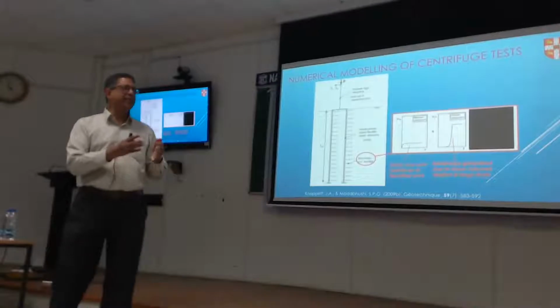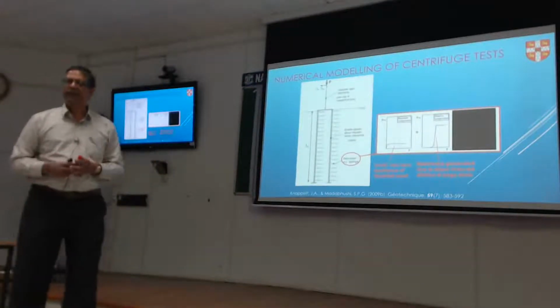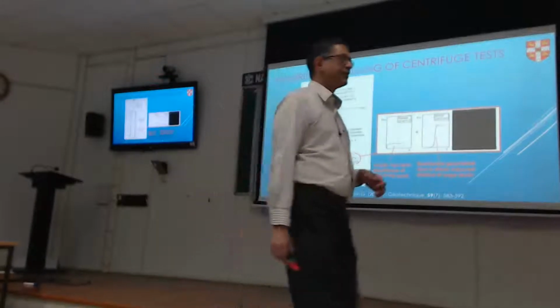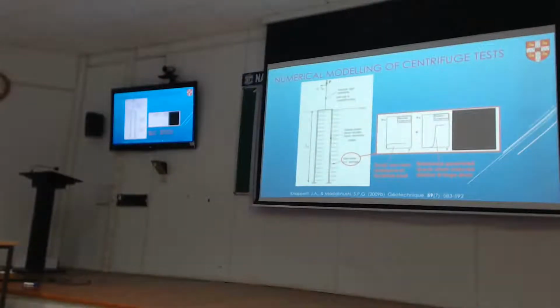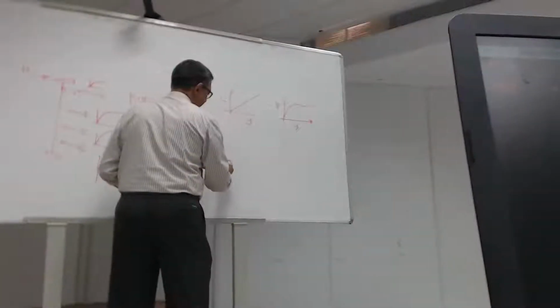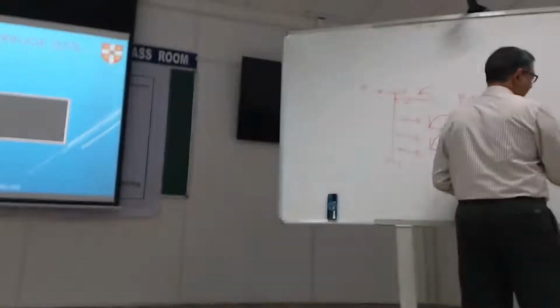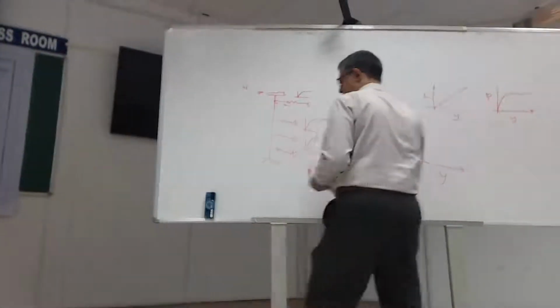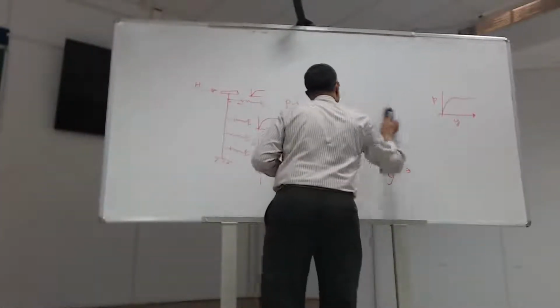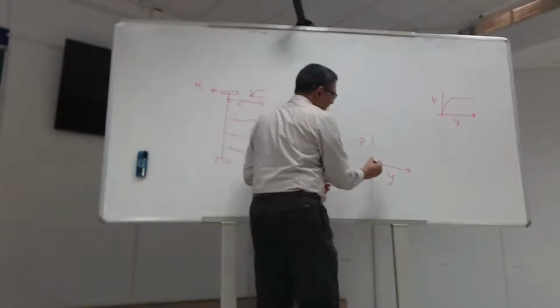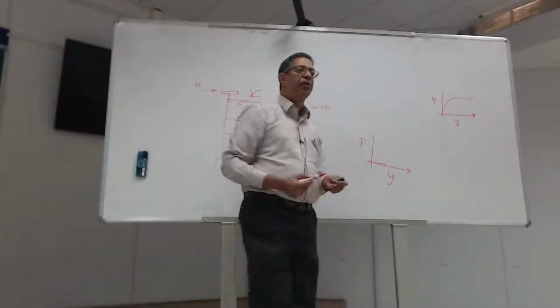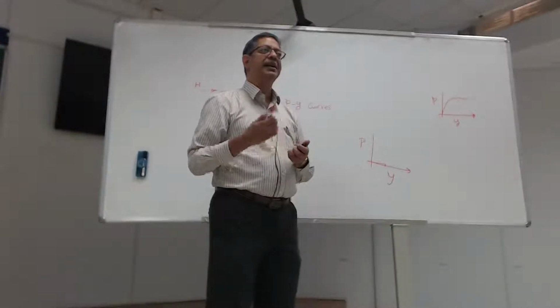When we are applying the same thing for a buckling pile, what we were saying earlier is that those kind of simple curves won't do. Because we know that with the liquefied soil, as the pile tries to go through it, initially it does not do anything because it needs some strain or displacement. So I need a certain threshold displacement before the soil dilation kicks in.